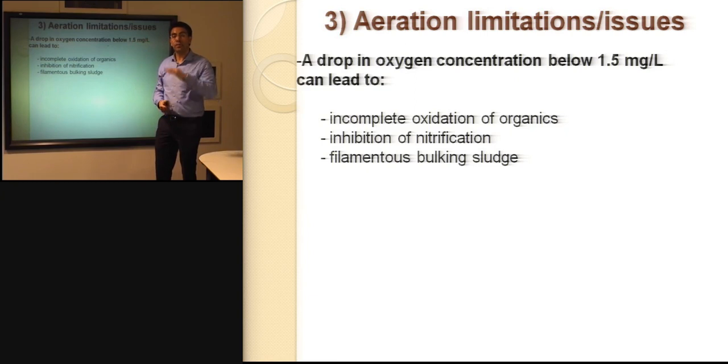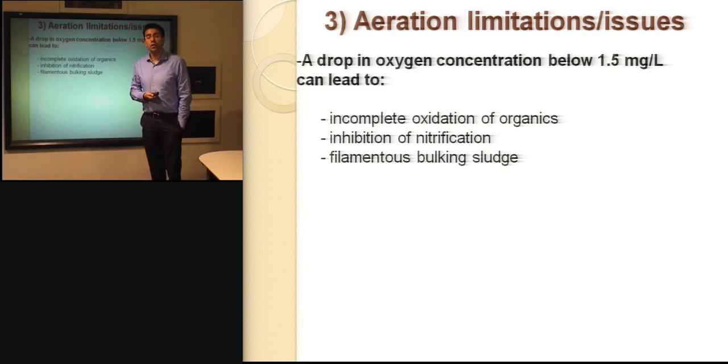And on the other hand, if it doesn't reach enough compaction in the bottom of the secondary settling tank, there will not be the possibility to recycle enough back to the activated sludge plant to keep the desired concentration of organisms in the system. So overall, these conditions, a drop in oxygen concentration, can lead to a complete deterioration of the wastewater treatment plant.